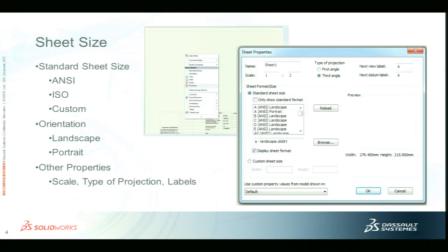In Europe and Asia, most of the time they're using the first angle. So just remember, if you go through and put in the drawing views and they don't look right because the top view, instead of looking from the top down, is actually looking from the bottom up, then you've got the wrong angle of projection selected. Okay, that's the biggest portion of the difference between third angle and first angle, is the way that the top view is looked upon.